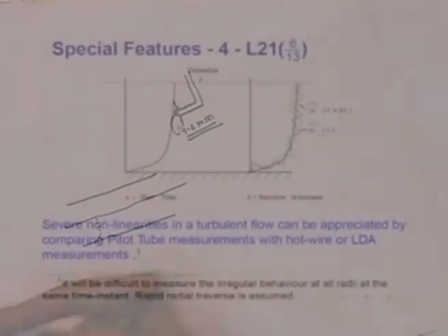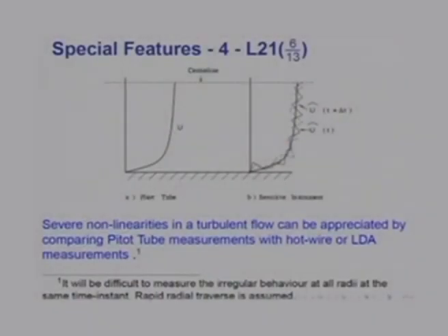facing in the axial direction, then the pitot tube of course does not see any randomness, any unsteadiness at all, because the flow is steady on the mean, that is, your compressor or the blower is supplying the mean velocity at a constant rate, and therefore it sees the time average value of the velocity.